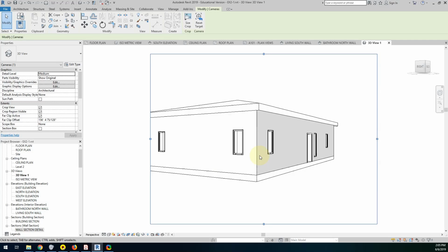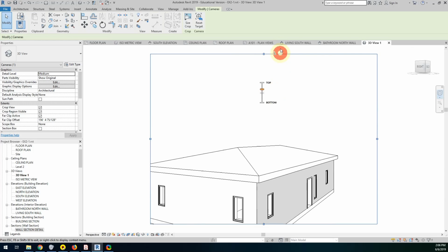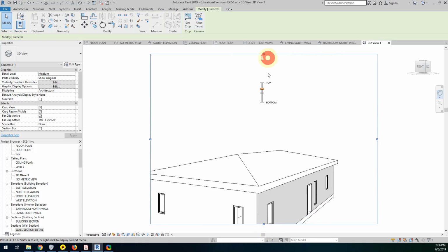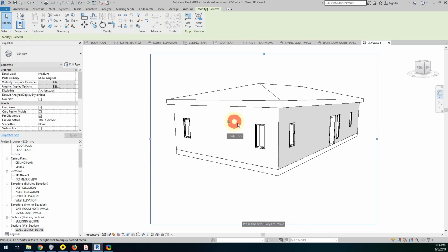And then it will go to that camera view. And this takes a little getting used to. There's a little steering wheel off on the right-hand side of the navigation bar. If I click that and move my mouse around, you'll see it stays connected to the mouse or magnetically connected to the mouse. You can choose options like move up and down. So if you click and hold and move your mouse up, you'll see it keeps repeating, going off the screen. Or you can look, which pivots the camera.